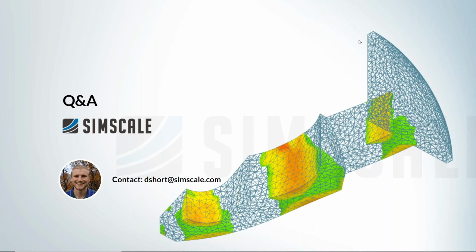But that's really left in the hands of the designer. We're there to give you the results, and then that's going to have to be on your design expertise, saying how can we then reduce stress concentrations by adding fillets, for example, allowing smoothing out of those stress lines throughout the model.